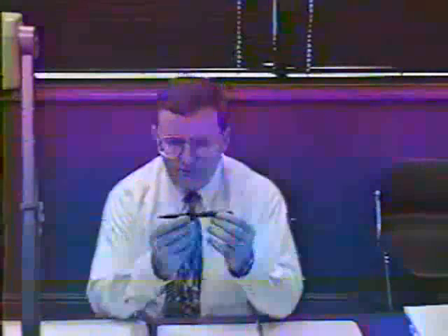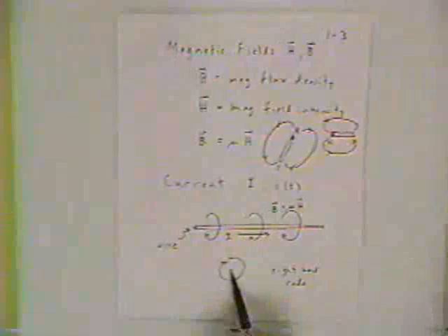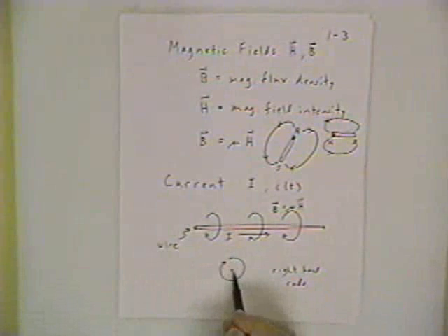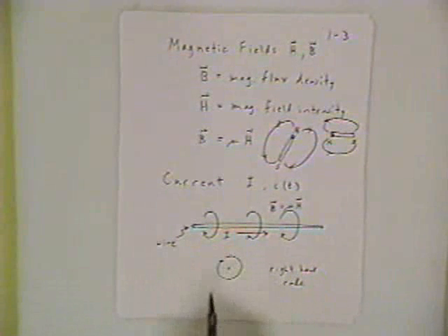One thing to keep in mind is the famous right-hand rule, which says the following. If this pen is indicating the direction of current flowing this way, I can line up the thumb of my right hand with that direction of current, and then the fingers of my right hand curl around. If you watch, the pen is going away from the camera, my thumb is following the direction of the current, and the field lines are wrapping around according to this right-hand rule fashion. So you can see that same thing here on the screen. If you just imagine that this is the point of an arrow coming up, then your right-hand fingers would curl around in this counterclockwise direction.